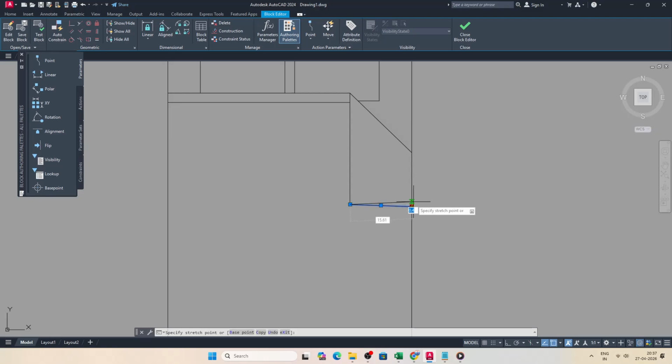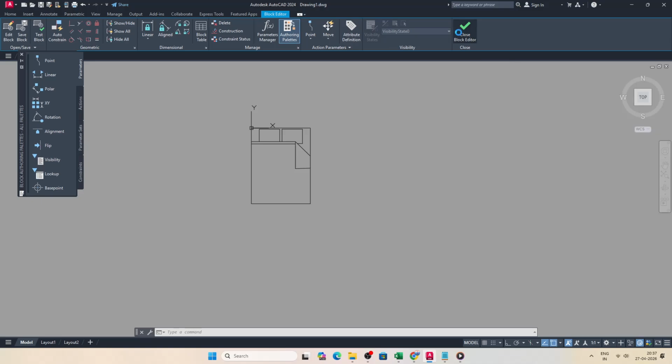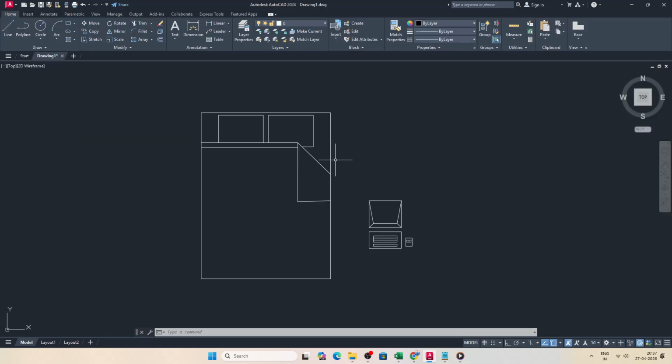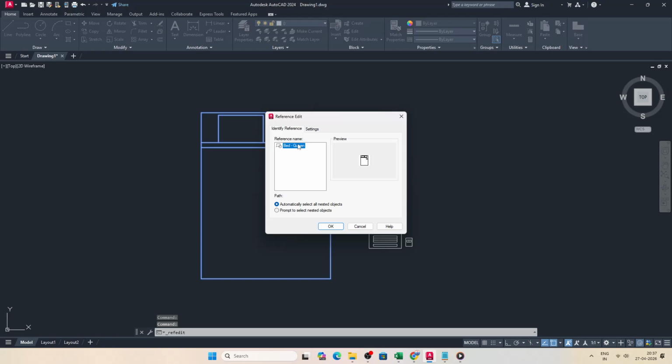Now, if you prefer to see your edits while the rest of the drawing remains visible, use Edit Block in Place, also known as Refedit. Right-click the block and choose Edit Block in Place, or type Refedit. The block becomes editable where it sits, and you can immediately judge alignment, spacing, and relationships with nearby objects because everything else stays on screen.